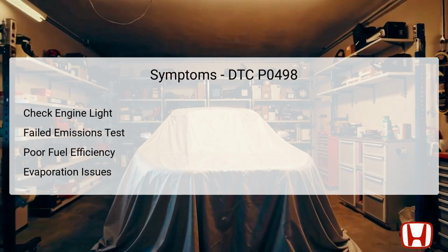The symptoms associated with DTC P0498 can manifest in several noticeable ways. The most immediate indicator is the illumination of the check engine light, alerting the driver to a potential issue requiring attention. If unresolved, this fault may lead to a failed emissions test, negatively impacting compliance with environmental regulations.